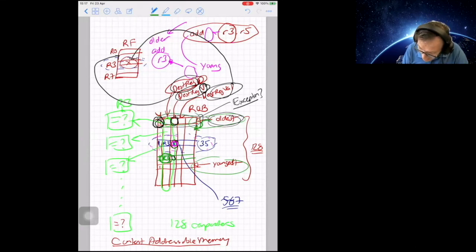Now this entry becomes invalid. It becomes 0, right? So that's the global valid bit. The global valid bit means whether or not you have allocated something in the reorder buffer, because it's a limited size structure. You may actually have zero entries in the reorder buffer if the pipeline is just flushed, for example. Okay, so that's the operation of the reorder buffer. Hopefully it's clear, or more clear right now. And we're going to solve this content addressable problem right now.